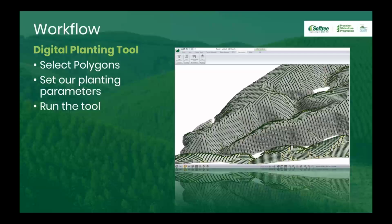Here we'll select the polygons, set our planting parameters, and run the tool. And as Tim mentioned, then we can export it. Avenza is a really cool format. We can send it out to Avenza, which is basically creating a geo-referenced PDF you can access on a mobile device or on any other device that has GPS attached to it. We can also export out to shapefiles, CSV, or our fancy paperspace tool, which we call Multiplat. And so that's it: terrain model, create some block boundaries, discretize those into polygons, run the planting tool. Now into the fun stuff.